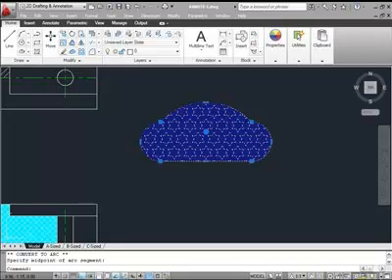It's set to not plot for performance optimization. But you can absolutely turn the plotting of transparency back on if that's your goal when you get to your plotting stages. And don't forget, transparency can only go as high as 90, just to avoid confusion with frozen layers or turned off layers. So don't forget that if you keep trying to put in 100 and it's not working, that's why.